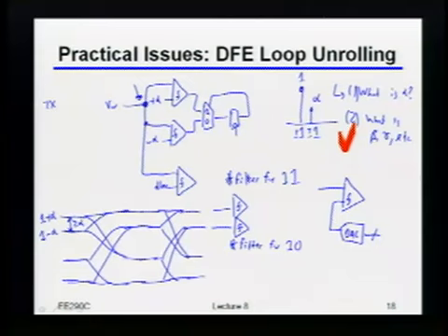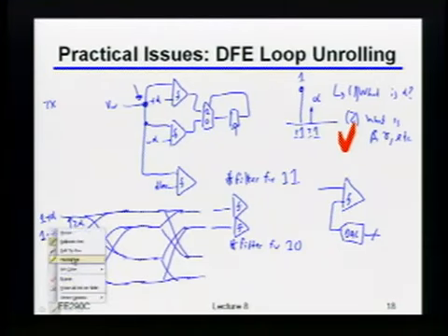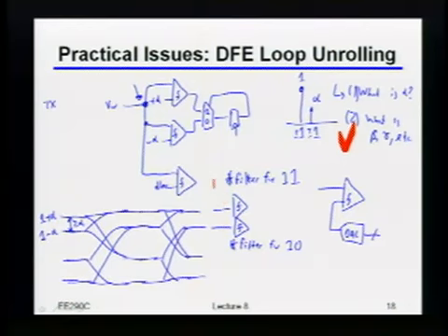A subtraction. Okay, so you do a subtraction at the bit rate. Well, I won't actually do this at the bit rate because hopefully the channel's not changing that fast, so maybe I do it at the deserialized rate. Yeah, there's some power saved from doing that, but let's not even worry about that because, like I said, this kind of has to be a hack because I have to jump between one level and the other level. While I'm doing that jump, I probably don't want to be adapting all my other stuff. So maybe I even do this offline. So yeah, I have to do a subtract, and then I divide by 2. Those digital operations work perfectly.